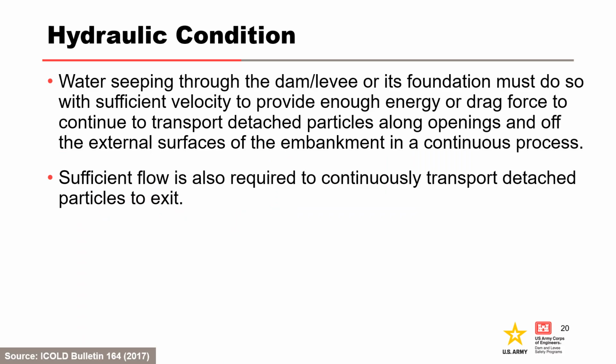For the hydraulic condition for progression, water seeping through the dam, levee, or its foundation must be doing so with sufficient velocity to provide sufficient energy or drag force to continue to transport detached particles along openings and off the external surfaces of the embankment in a continuous process. Thus, there must be sufficient flow to continuously transport detached particles to an exit.